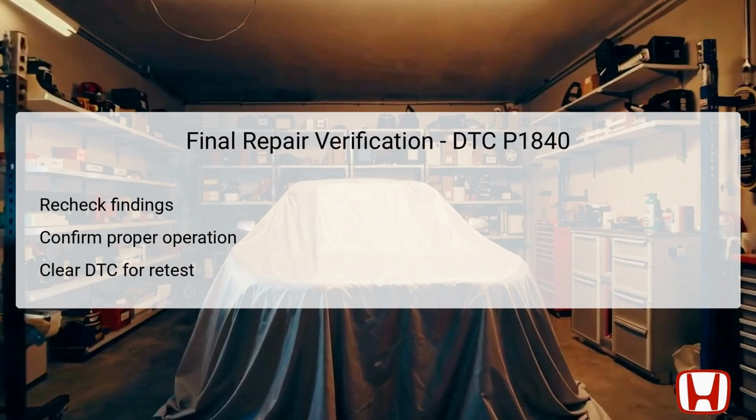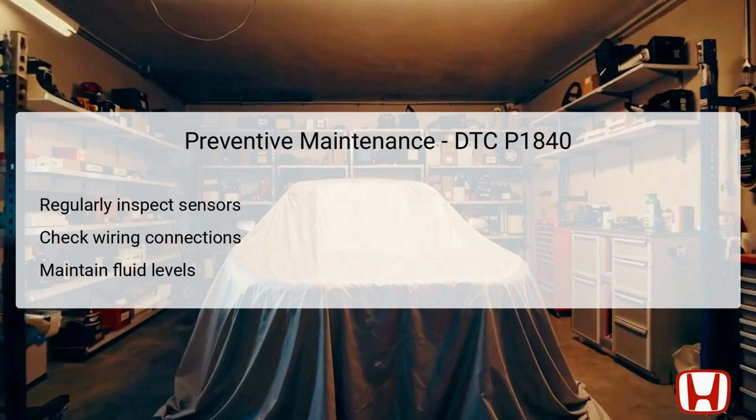Once you are satisfied with the repairs, clear the DTC from the vehicle's computer using the HDS. After clearing, it's imperative to retest the vehicle under similar conditions to those that initially triggered the DTC. This ensures that the repair was successful and that the vehicle is functioning as expected without re-triggering the diagnostic trouble code.